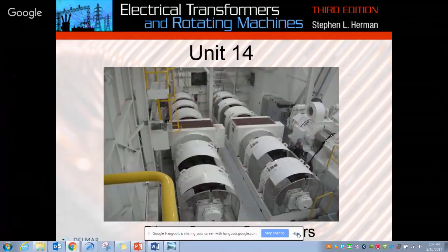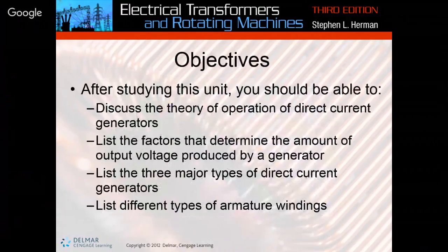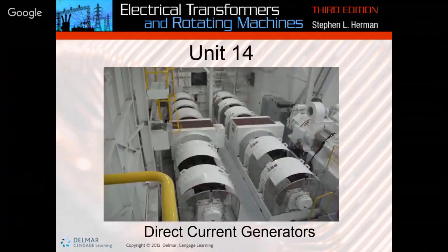This right here, this picture, is a DC generator inside of a dragline. How this guy operates, we have two AC motors hooked up right here, and that's what's going to generate our mechanical energy. These AC motors are hooked up with the shaft spinning on both sides. That's going to be the mechanical energy to turn all of these DC generators to give us an output. Okay. Story, you can go over there to Wyoming, you're going to see this. I promise you.